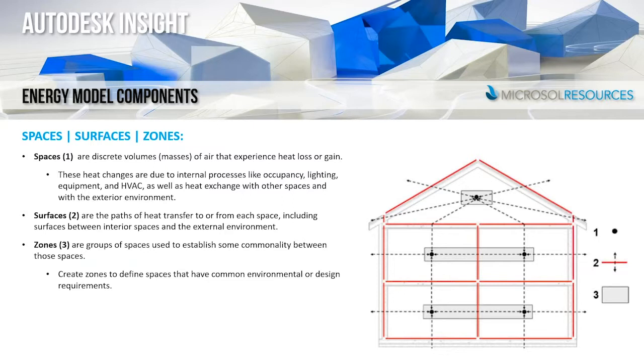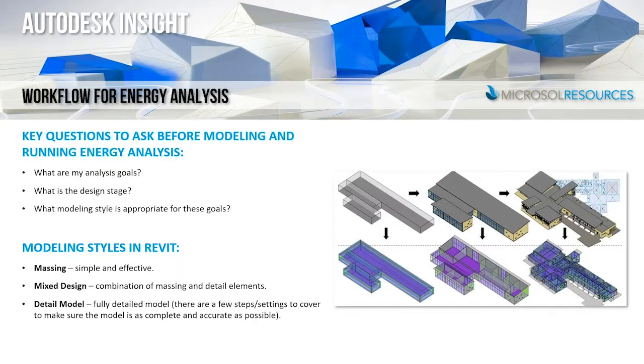And by default, any elements when they're created in Revit will be checked as room bounding. So if there was something you didn't want to be room bounding, more often than not you would be unchecking that room bounding setting as opposed to checking it. Some of the major elements that can be used for room bounding are ceilings, columns, curtain panels, curtain systems, curtain wall mullions, doors, floors, masses, roofs, soffits, shaft openings, site pads, walls, windows. Most everything that you're going to use for your actual model itself is going to be used in the calculation as long as it's set to room bounding.